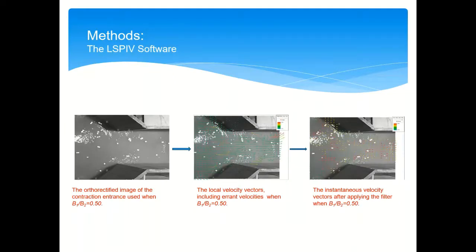In this study, software for LSPIV was used for measuring the vena contracta width. The LSPIV technique calculates the movement of paper tracers on the water surface flow to and within the contraction. Most of the applications were done once the contraction scour had attained an equilibrium condition. The flow is seeded with paper pieces, and a video is taken. Then the video is uploaded into the software, and the procedure includes orthorectifying the images.